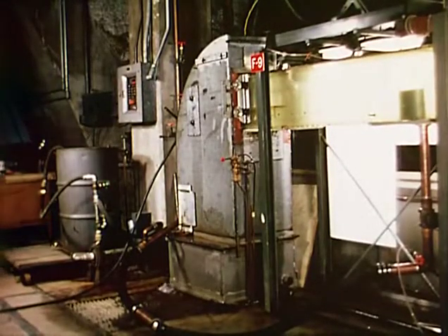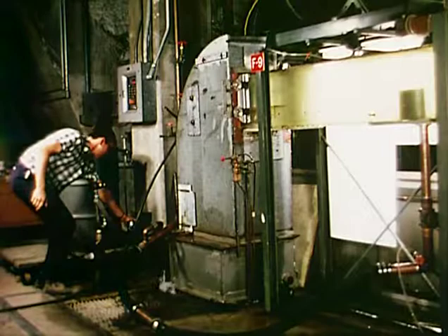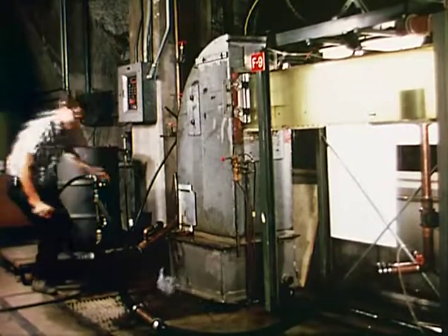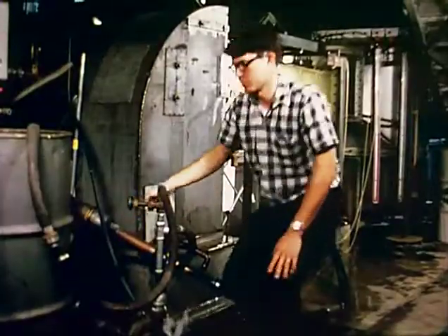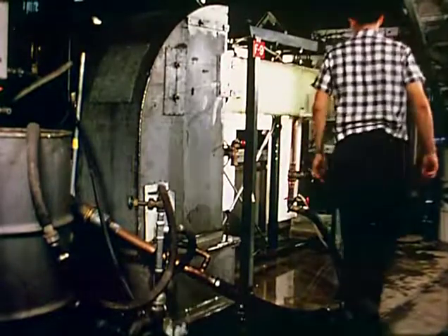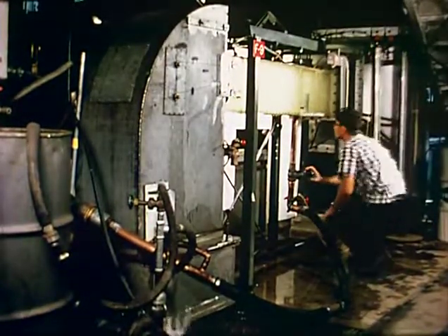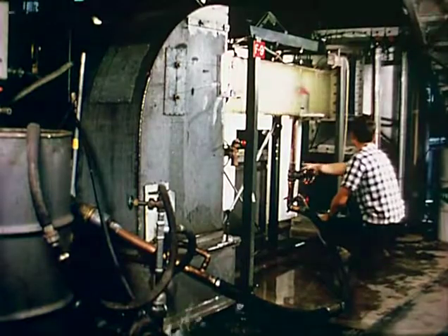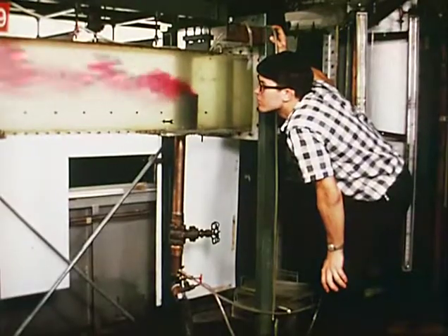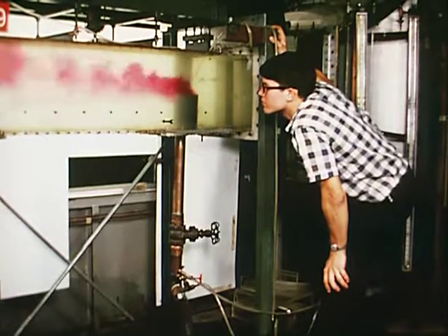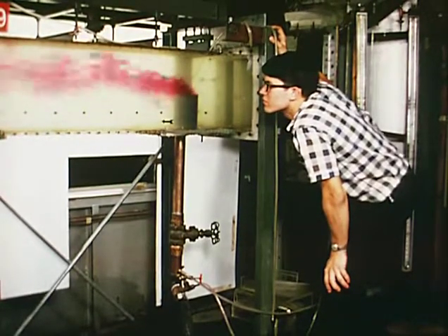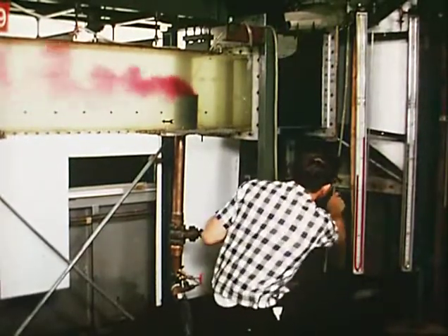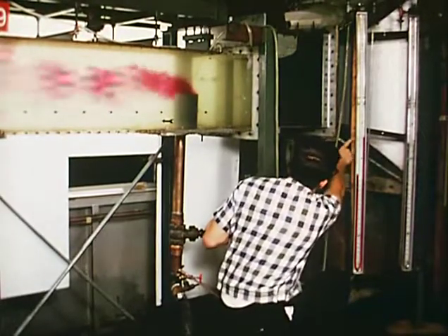Additional experiments were performed on a small full-scale injection nozzle. A special water tunnel in which it was possible to simulate a typical pipe boundary layer of a larger pipe was used. With the flow through the tunnel set at 5 feet per second, the supply to the nozzle is activated. The tunnel flow represents a mean velocity of 5 feet per second in an 8 feet or larger diameter pipe. The nozzles tested were 2 inches in internal diameter and extended 6 inches into the flow. The speed of injection is 5 feet per second.